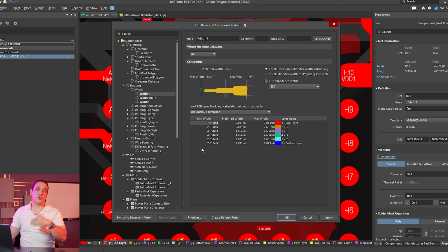However, if you create a transmission line table inside your manufacturing documentation, it will import that 5% value that you defined in that impedance profile and automatically fill it into your transmission line table, and then you can hand that off to the manufacturer for controlled impedance testing.